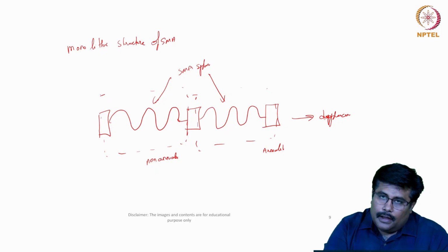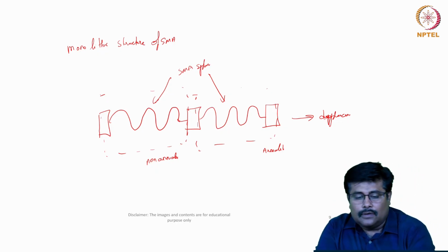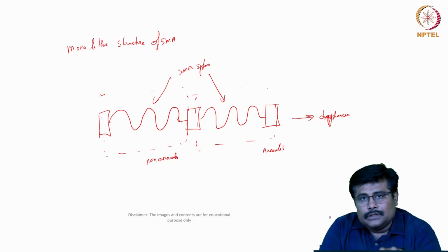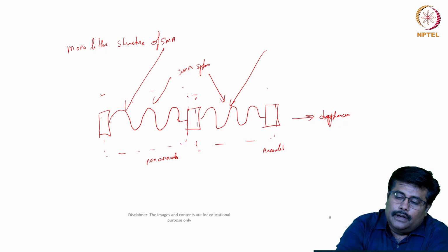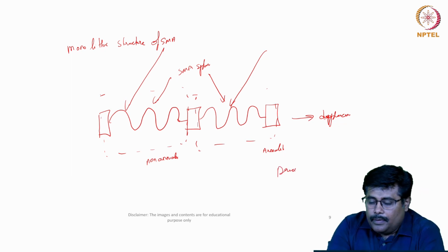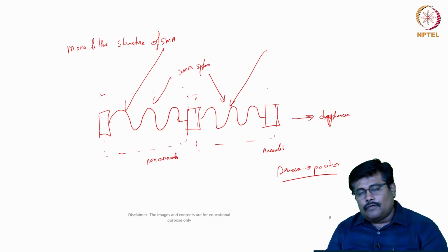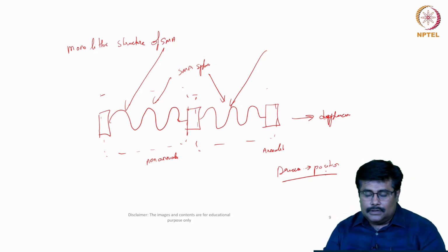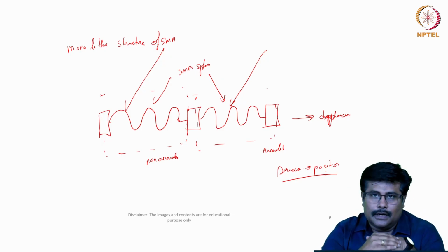In fact, in order to take care of higher-order precise control, here the actuation is through thermal. We can also use a laser. When we irradiate with the laser, appropriately we can have a precise positioning of the system. So these are some configurations which are available for creating these monolithic kinds of structures for SMA related applications.